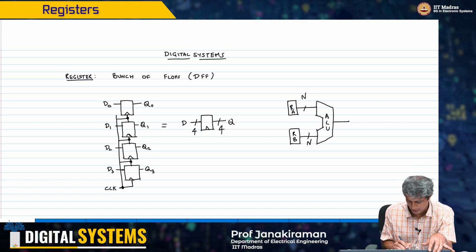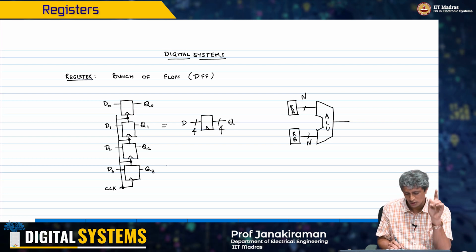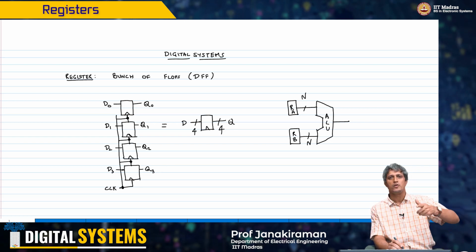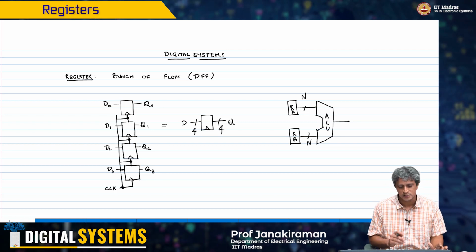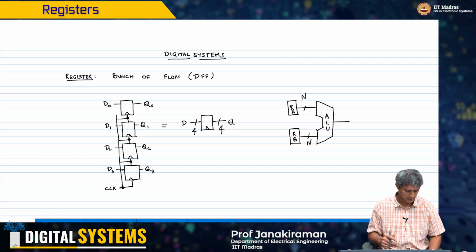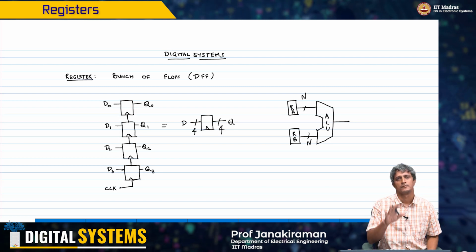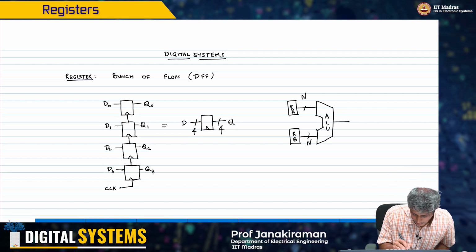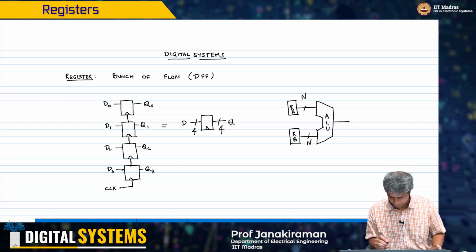Okay, this is what I mean. So only where there's a dot, there's a connection. If the clock crosses D3 to D1, it doesn't mean there's a connection there, okay? So essentially this is what I mean by this other picture where the clock was running underneath and I'm just making the contact to the clocks here, okay? This is just a less cumbersome way of drawing it, okay?